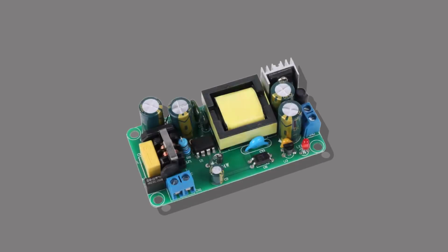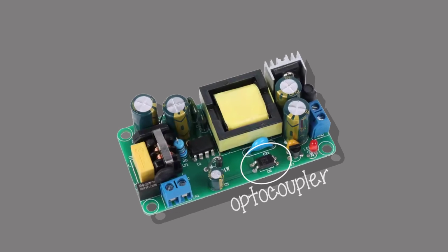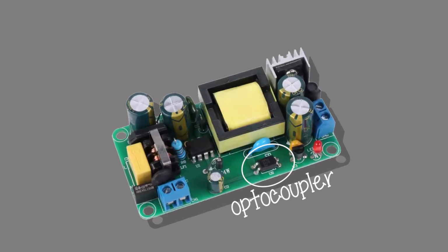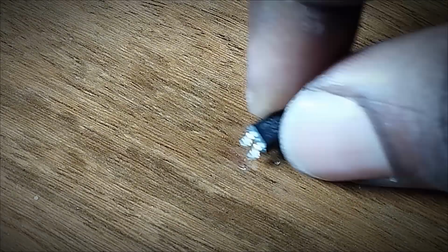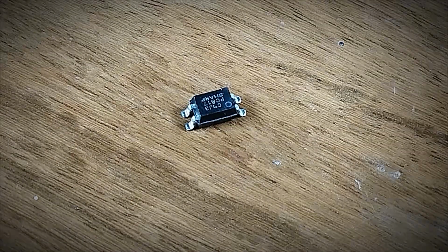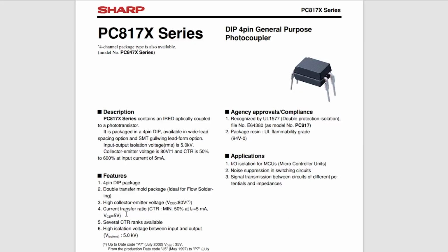This way, both circuits can remain isolated but communicate. They are widely used in power supplies for feedback control, isolating the high voltage parts from low voltage parts, but passing enough information to properly regulate the output voltage. Also, they can be used by DC circuits to switch AC loads, like the case of optotriacs and others. So let's look at parameters to consider before using an opto isolator.